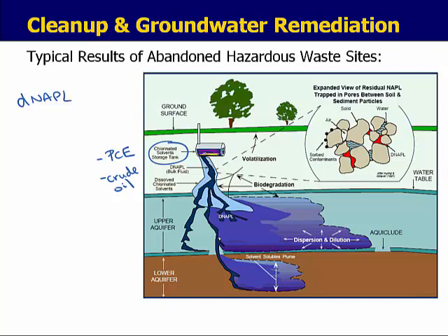So in this instance, when that contamination occurs, the plume here will sink, and when it interacts with the water table, you will have some of that dispersion and dilution and less concentrated plumes that move into the water table. But the main plume, the main concentrated plume, will continue to sink.